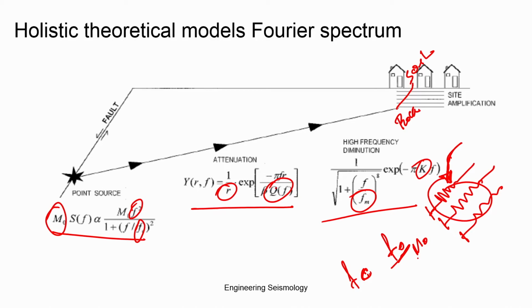Most people who use synthetic ground motion simulation, or use these factors in their analysis, simply take factors derived elsewhere and use them here as input parameters. For the first time, we did a regression analysis of the data collected from the Himalayan region and estimated all these factors for the Himalayan data, which we also published. We used them to generate a synthetic ground motion, and from that ground motion we obtained a predictive equation for ground motions at different frequency or period levels.